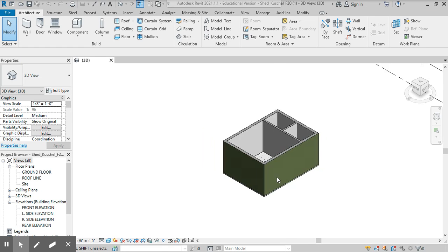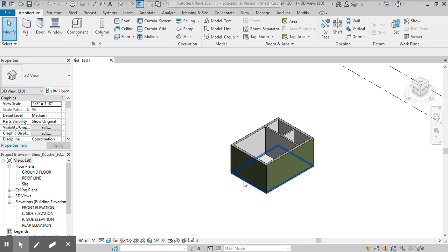So a couple of things once we're inside of Revit that you'll work with. We have two areas we deal with quite a bit. One is called the project browser, and perhaps you remember a browser over here in Inventor, so similar to that. Then we have a properties palette, is what we call this top portion. So this is one portion of this window on the side, and that's called the properties palette.